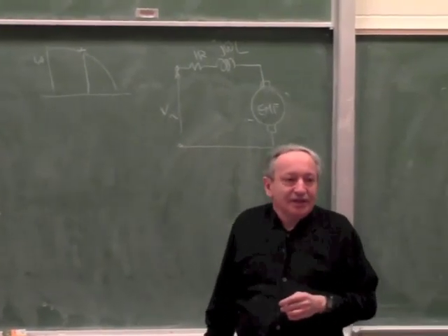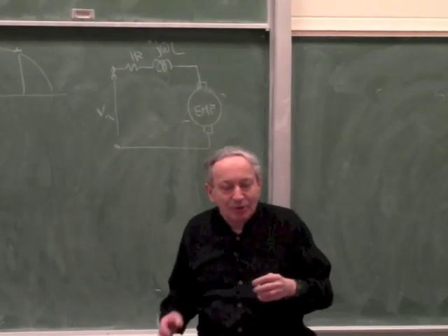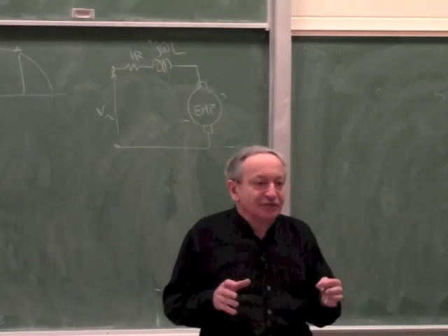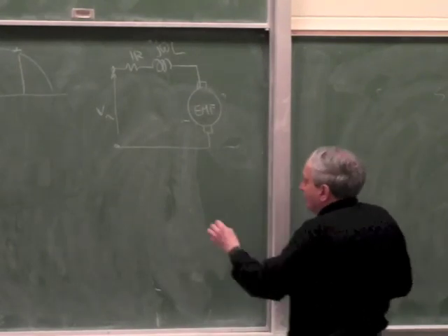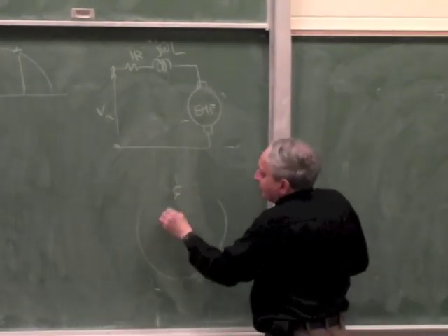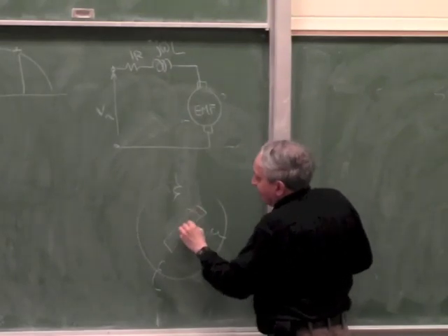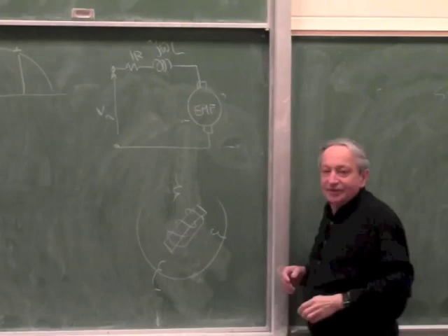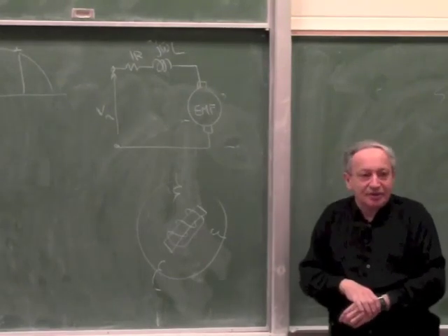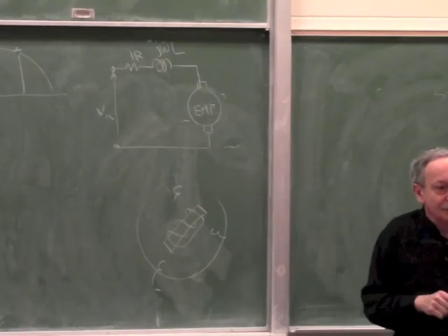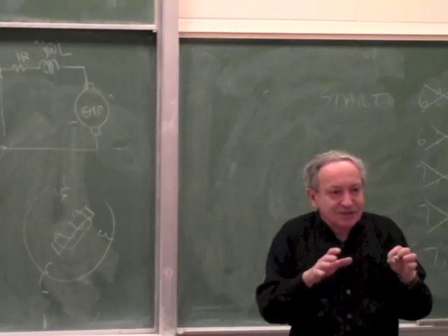What does that mean to optimize? What it means to optimize it is that the induction motor is really a transformer. Because what happens, as I drew before, you have coils here, and you have a rotor here with the equivalent of a coil which is shorted. Now, when you have a model of a transformer, did you learn in electrical engineering what a model of a transformer looks like? I can just explain very briefly.